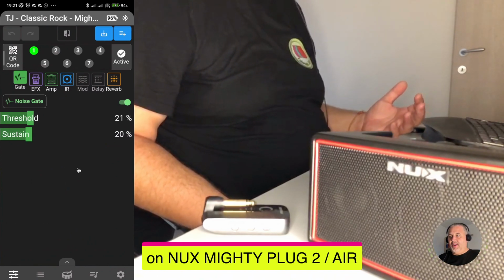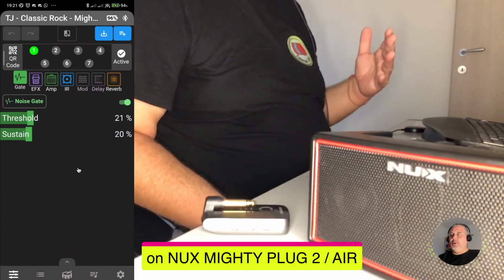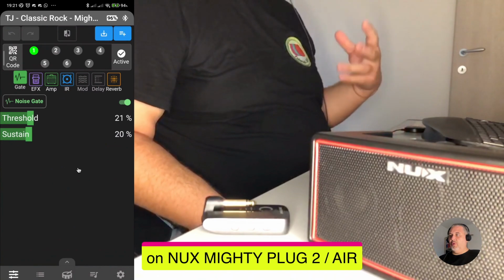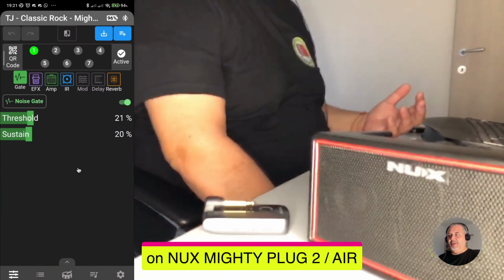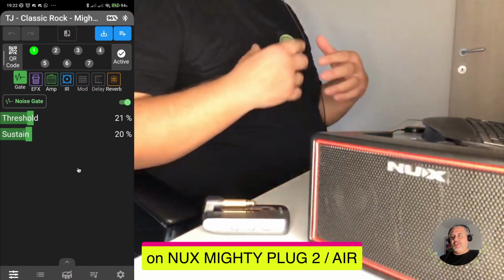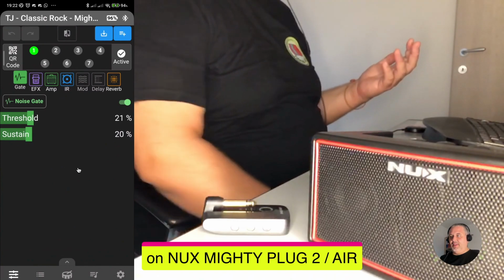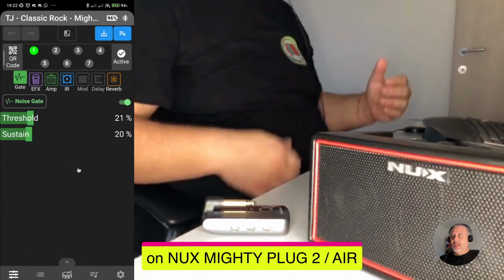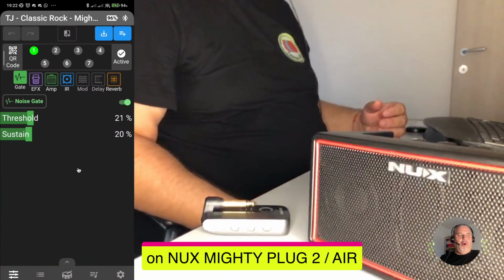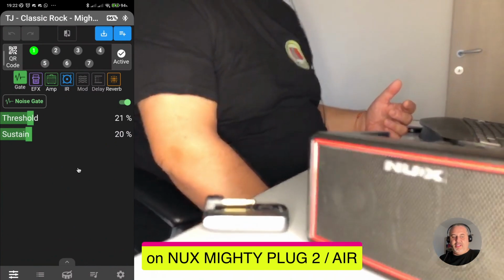That's common in any kind of electronics. Any amplifier has a saturation limit, and that is why normally it is limited with a compressor or something like that, in order to avoid distortion. Because when an amplifier is reaching its limit, it's not replicating exactly the waveform it receives as input signal, but is cutting it at the top or at the bottom, and the result is a more crunchy sound, the distortion, what we feel as distortion.